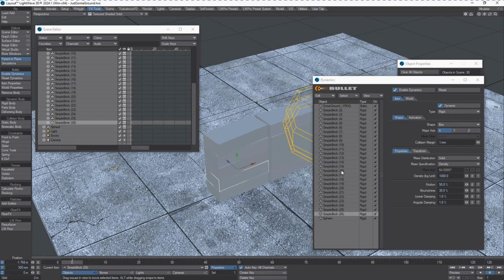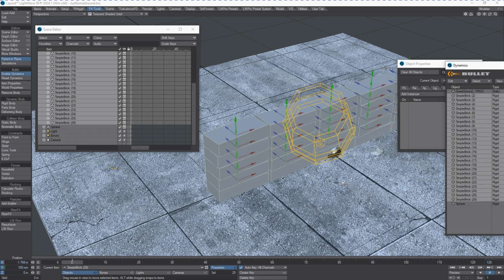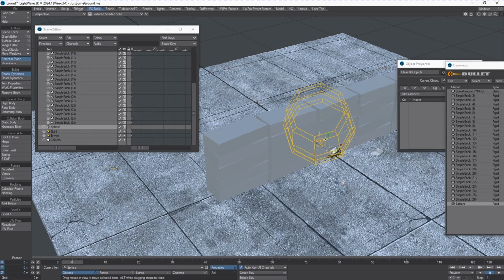And because these bricks are under the influence of gravity and there's a little bit of space in between them, I'm just going to turn the activation mode, once they're all selected, to start sleeping. That way, once we've got our sphere selected and it makes contact with the collision objects for the bricks, they'll activate and they won't move right off the start.